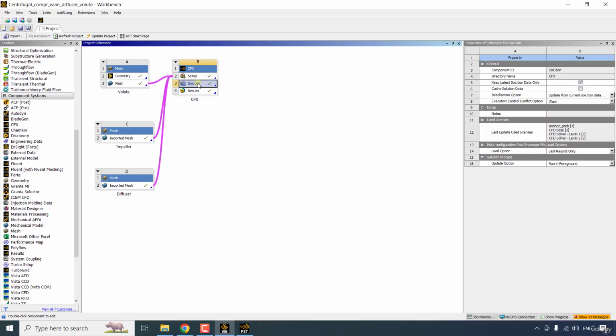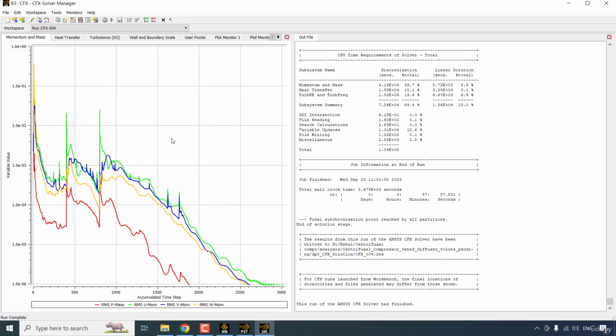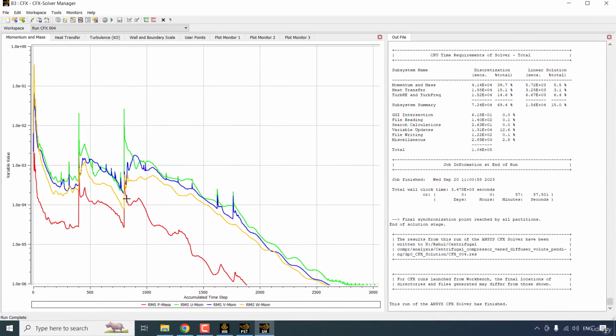In this simulation, the main thing is to run the case with lower back pressure and then continue with the higher back pressure. Whenever you are giving the higher back pressure, automatically the earlier case, that is the lower back pressure case, will be given as the initial condition in Ansys workbench. So it will be easy to solve the case from the given initial condition.